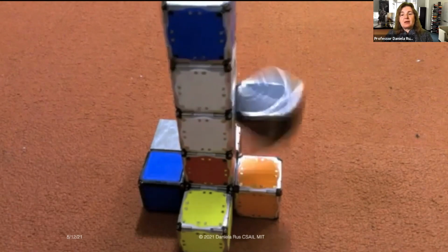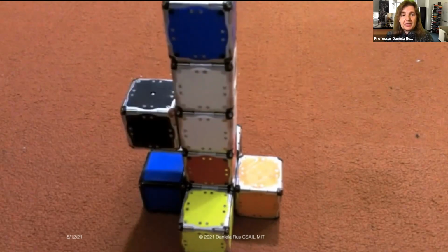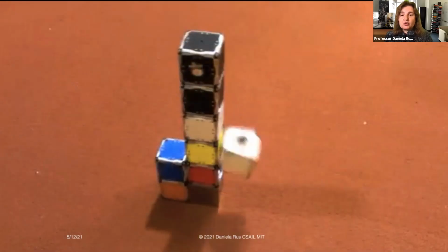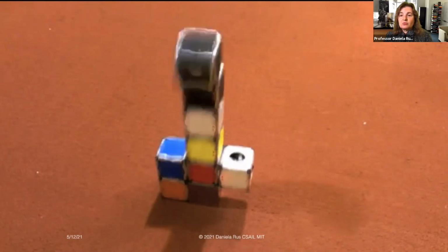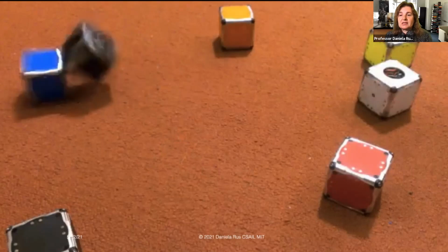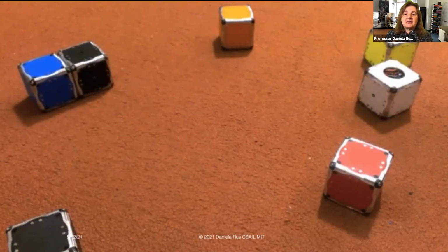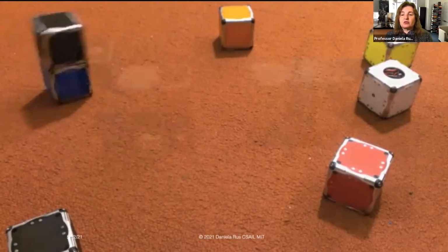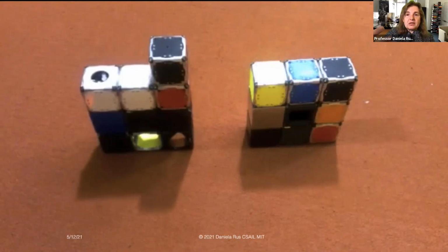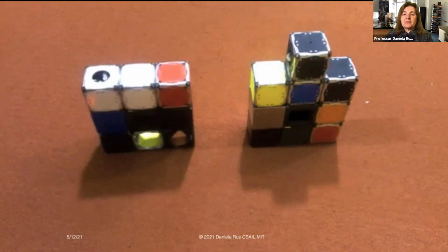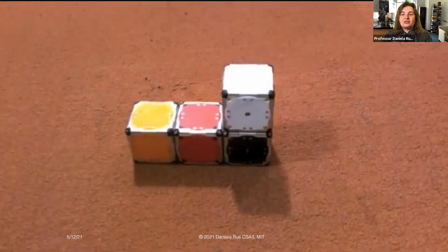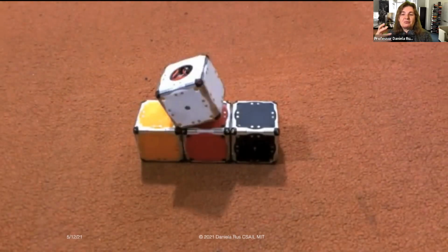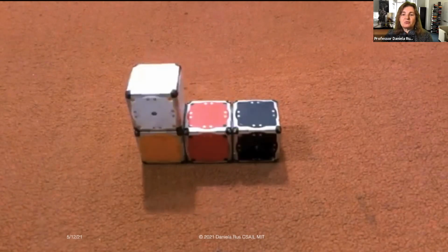And this is an example from my lab called the M-block. The M-block is a 2-inch by 2-inch cube that can move by pivoting. And the secret to the movement is a flywheel inside the robot that spins very fast, and then a braking mechanism stops the cube suddenly. The stored momentum then propels the cube forward. And so the M in the name stands for magic, because with no externally visible moving parts, we feel like the robot moves as though by magic.